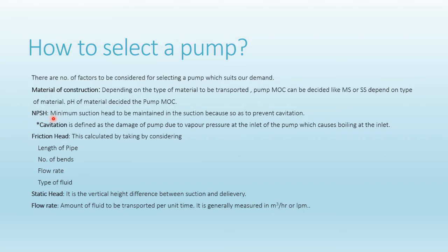NPSH, net positive suction head. Do you already know cavitation is a process in which, when the suction pressure is below the vapor pressure of that fluid, boiling of the liquid will occur at the suction side, which in turn damages the pump internal casing. So what we'll be doing is increasing the suction pressure above the vapor pressure so that no cavitation will occur at the suction of the pump. So every time NPSH has to be considered for selecting a pump also.